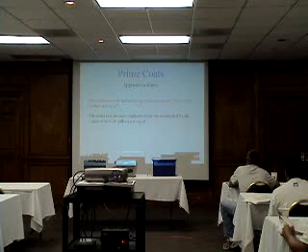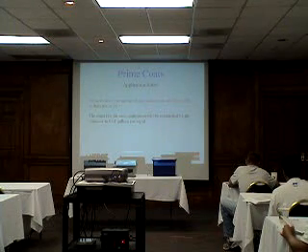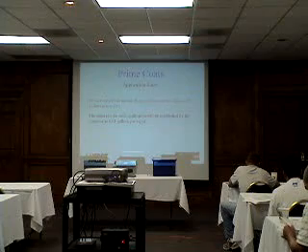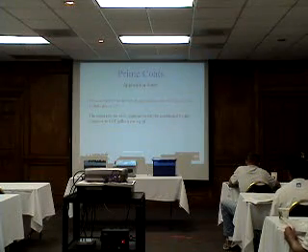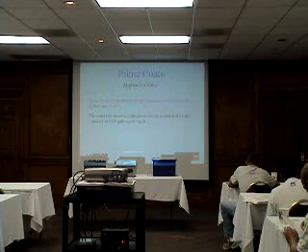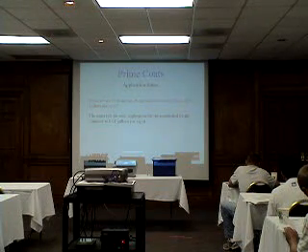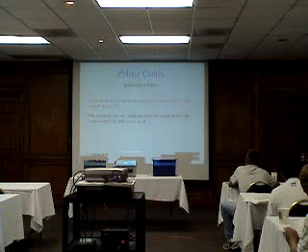The exact rate of that prime coat application will be given to the contractor by the engineer prior to beginning that priming operation. And it will be given to him to the nearest hundredth of a gallon. So he may say, Mr. Contractor, I want you to prime this at 3/10 gallons per square yard. I want 2/10 gallons per square yard. He will let you know.